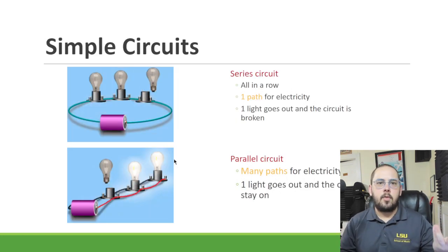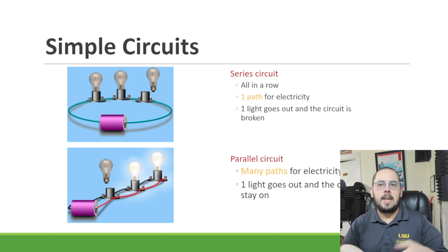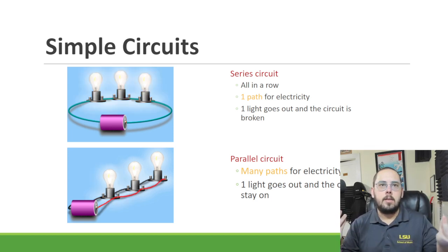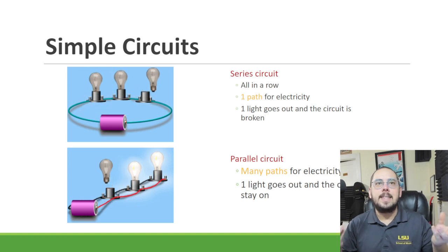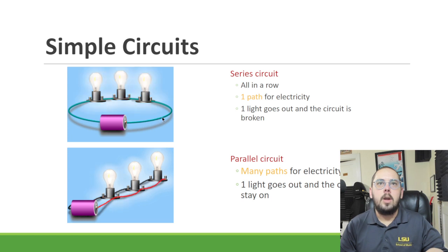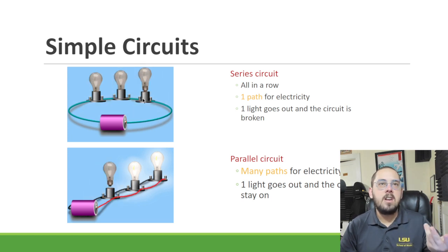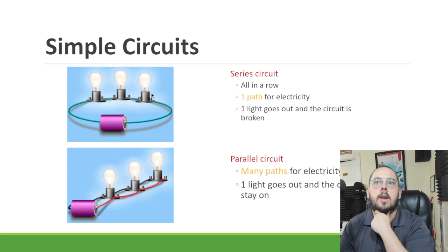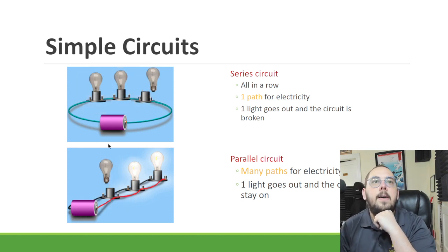You may have heard this phrase before, whether a circuit is parallel or in series. If something is in series, the power is going to go through one load to another, in order, before going back to ground. If something interrupts the series, the whole circuit is broken. This is different than in parallel.